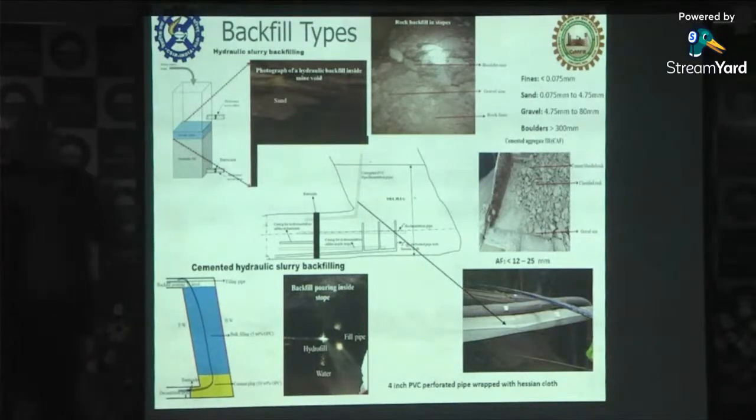If the design strength is like 250 kilopascal, and the reading is like 200 kilopascal during filling, then the filling is stopped, and when the pressure reduces to another like 150 kilopascal, then the stope bulk filling is done again. That has to be taken into account while forming the plug.